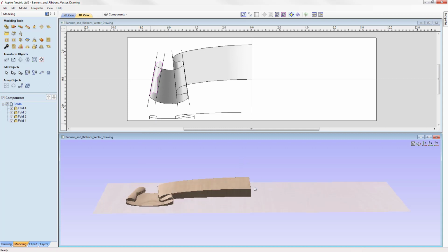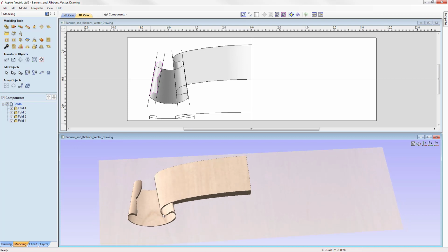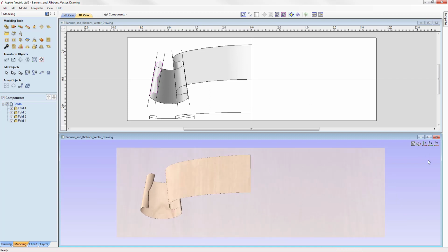And so hopefully this makes more sense into how the two-rail sweep works. And so the same technique can be used for any model that has this type of flow and folds in. For example, flags, linen folds, and banners for heraldry pieces. And there's lots of applications that we can use this for, and this same setup of vectors will work for that. It's just about the amount of folds that you have that will make it more or less complex.